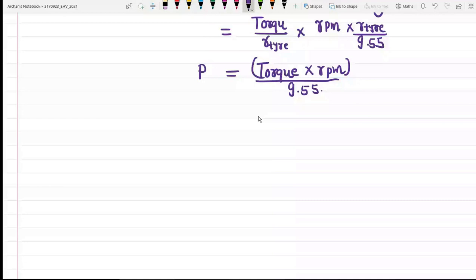But generally, if you require very high starting torque, then the rating of the motor should be very high. But when we get a motor with high rating, of course its cost, as well as its size and weight, will be quite large, and we have to set this electrical motor within the vehicle only, right? So every time it is not possible to use a motor with very high rating, because it is costly and bulky also, right?